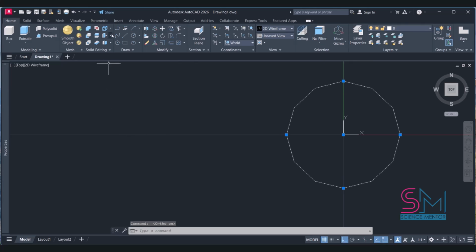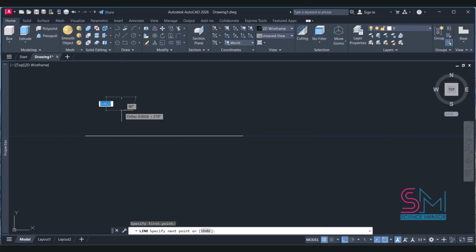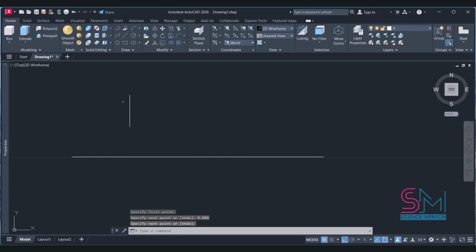Now I'll draw a line that's 0.03 meters long. This will act as part of the guidelines for shaping the propeller. It's a good idea to turn on Ortho mode F8 to make sure the lines are perfectly straight. With that on, I'll go ahead and carefully draw the rest of the guidelines.